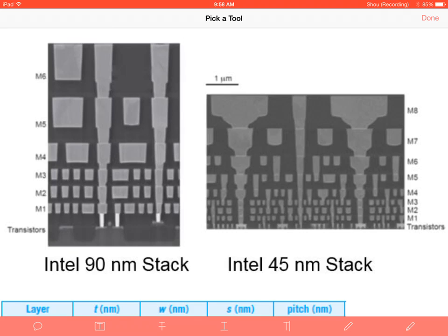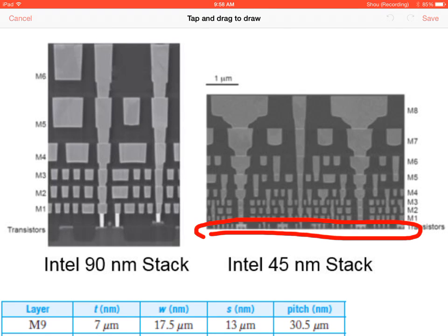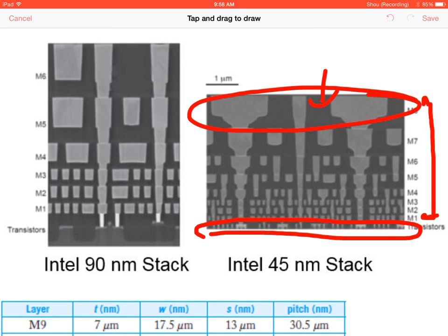So in order to communicate between the different stages, in order to account properly for horizontal and vertical spacing, you end up having 6 different metal layers. Once we get down to the 45 nanometer technology, your transistors are just here. This is where a transistor is. So then you have metal 1, and they're already up to metal 8. So this is where your VDD and ground are.